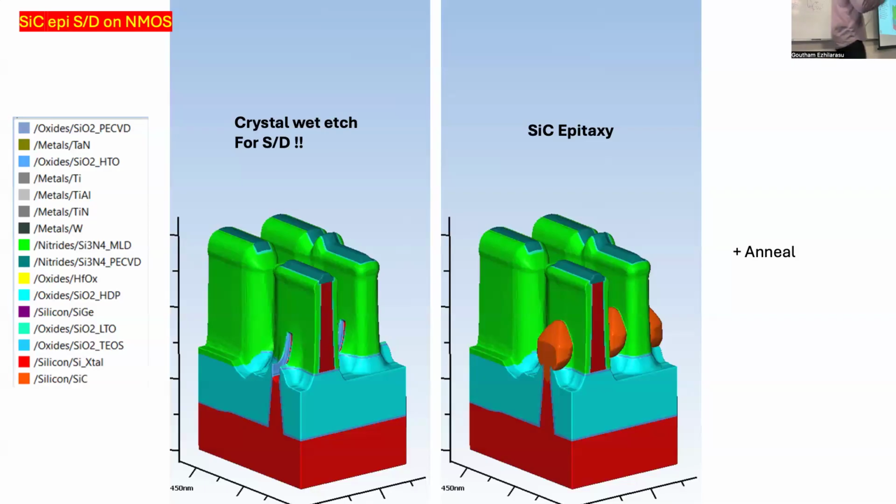No, because this is silicon carbide, right? So depending on which, see, basically what you're doing is you are creating this, so this is the channel, right? And then say originally this region had silicon, correct? So originally this region was silicon, right? If I take the silicon and I replace it with something that occupies less volume than silicon, it's obviously going to pull it, right? So if this was occupying less volume, it's going to pull it this way, correct?